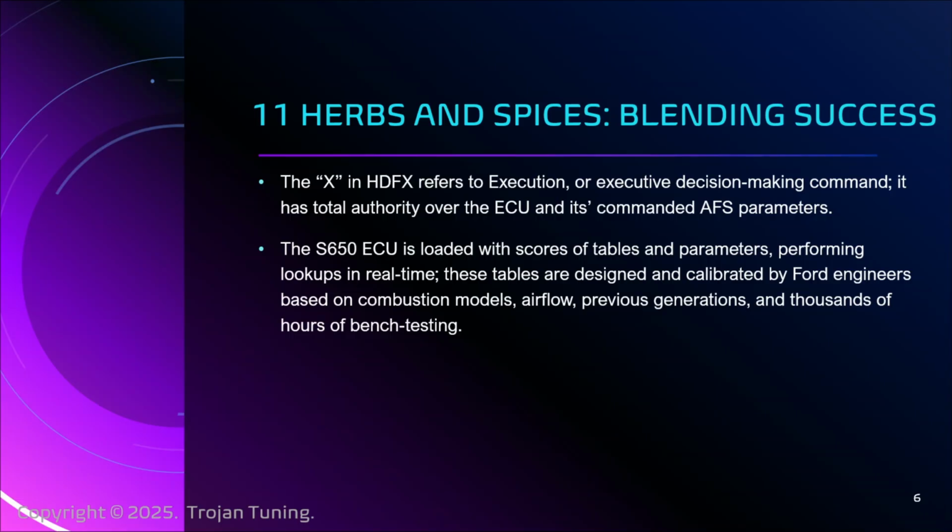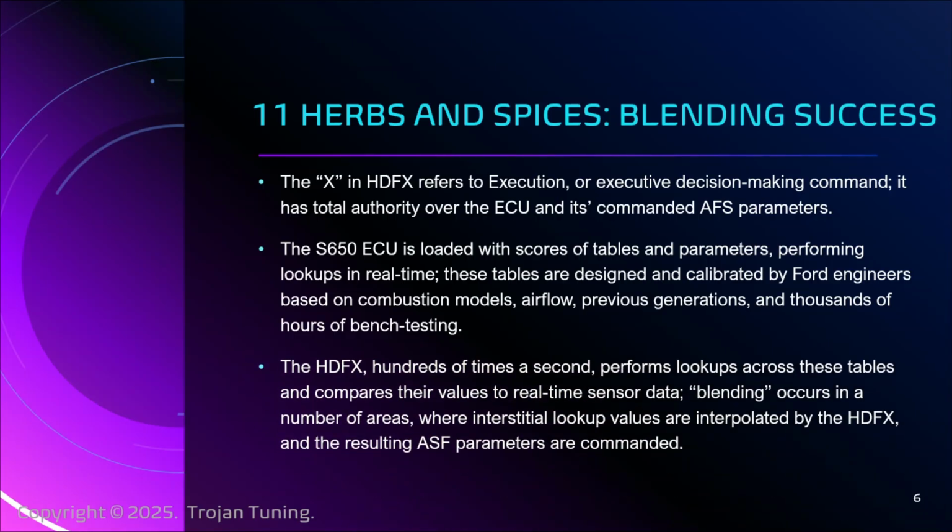They don't change, right? But the sensors are constantly changing. And so it can read the sensors, look at the lookups, decide what it is I want to do, and then from there perform all the calculations that need to happen to get me where I want to be. And the Ford engineers, they've done this for generations, so they're leveraging all the knowledge they have from the previous gens, and then on the current S650 and the Gen 4 Coyotes, thousands of hours of bench testing went into really perfectly calibrating these tables and the way this thing does the number crunching.